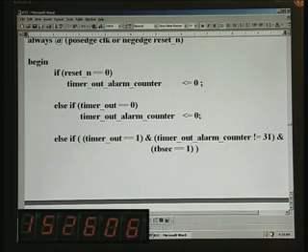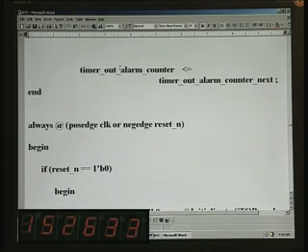That is why timer out not equal to 31. So, 30 means it has already sounded; when it is equal, it has already finished the sounding for 30 seconds, that is what it means. Then this will go low and this won't be satisfied, right. So, we need to satisfy this so that we may sound the alarm only for 30 seconds, that is the implication of this, and this should happen only every second, right. Otherwise you increment the actual alarm counter.